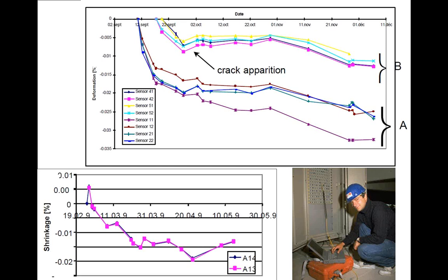An example of those results is shown in the graph here, where the onset of cracks could be identified just a few days after pouring, while the formwork was still around the concrete, and so the contractor could adjust the concrete mixture to avoid those cracks in the next pours. So those original defects could be identified and corrected early on.